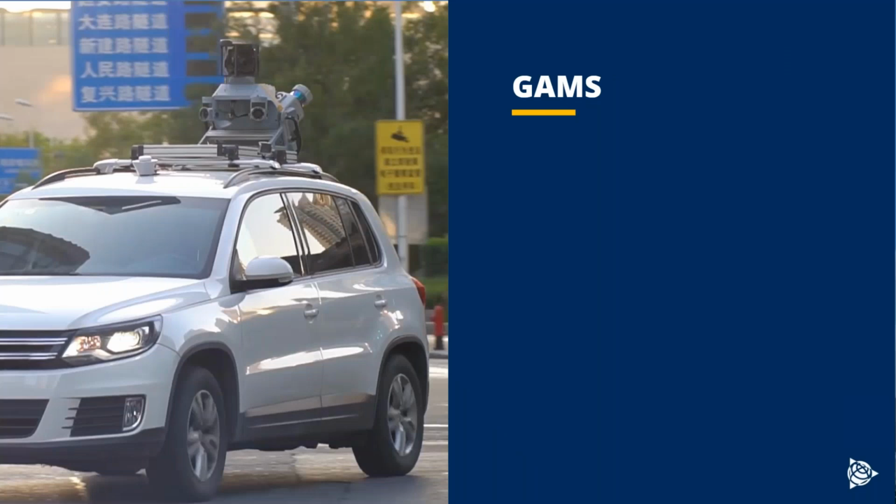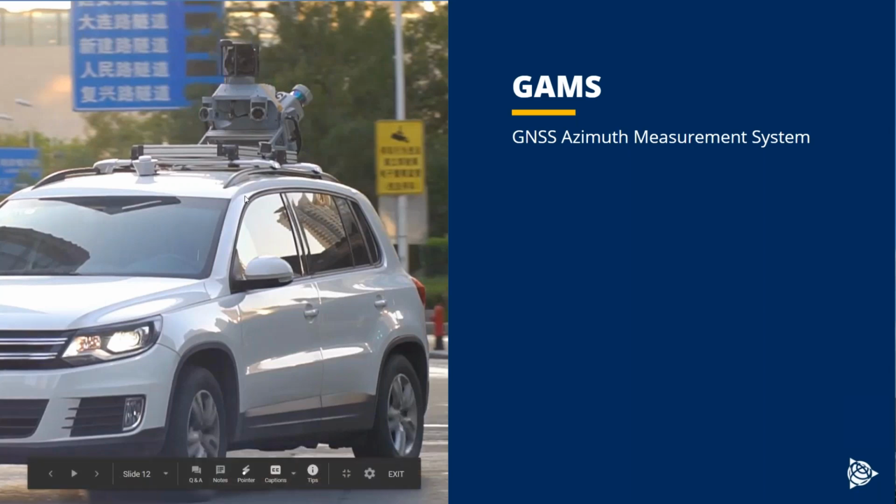First of all, I want to give you a reminder of what GAMS and DMI are. Let's start with GAMS. That's short for GNSS Azimuth Measurement System. It's basically a secondary sensor giving us heading information, so the heading of the vehicle and the mobile mapping system. If you look at the left side, there's a primary GNSS antenna at the top of the camera of the MX9, the black antenna here, and the GAMS antenna is the secondary antenna here in the front of the car in this image. So this small antenna here, that's the GAMS antenna.